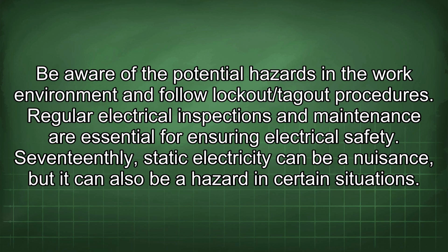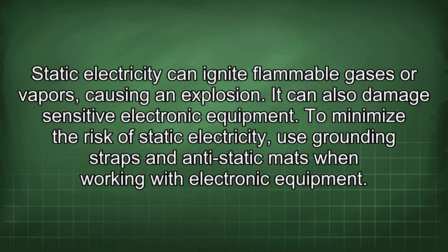Seventeenth, static electricity can be a nuisance, but it can also be a hazard in certain situations. Static electricity can ignite flammable gases or vapors, causing an explosion. It can also damage sensitive electronic equipment. To minimize the risk of static electricity, use grounding straps and anti-static mats when working with electronic equipment.